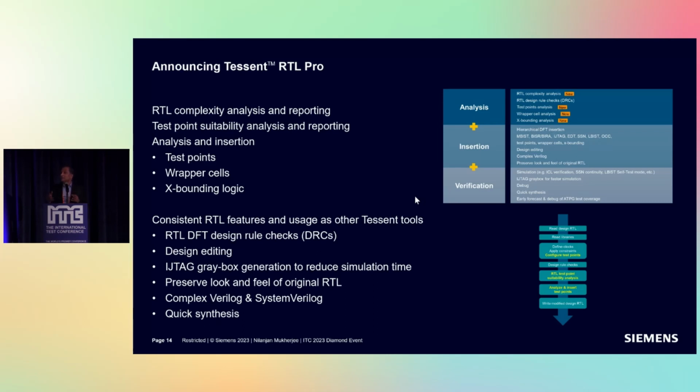Because there are certain designs, if it is completely very control heavy, everything is in the control logic, RTL test point insertion may not benefit you. You may have to do some parts of it at the gate level. So it actually advises you whether you can do the test point insertion or some of the other analysis at RTL or not.